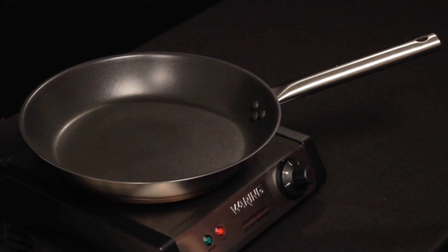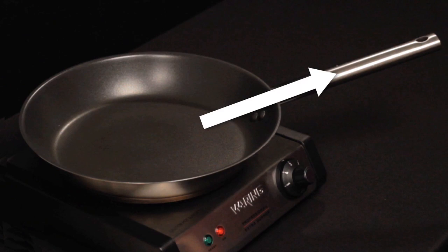Let's go back to our first case and refine our thinking. We originally assumed that the pan and the handle were in perfect thermal contact and that the pan and the handle were totally isolated from the room. Let's keep the first assumption, but change the second assumption. In other words, we will allow for some flow of heat from the handle to the room. Now what happens as we heat up the pan? We can assume that the heat flow rate from the pan to the handle is initially larger than the heat flow rate from the handle to the room.